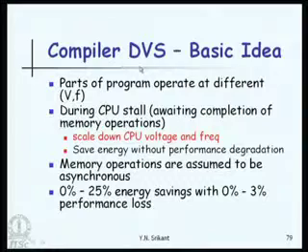Memory operations are assumed to be asynchronous. They go on independently of the CPU and they always operate at the highest voltage and frequency. It is the CPU whose voltage and frequency will be changed. Schemes of this kind have been shown to provide 0 to 25% energy saving with 0 to 3% performance loss.